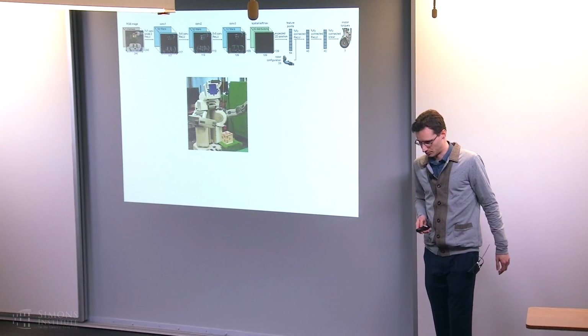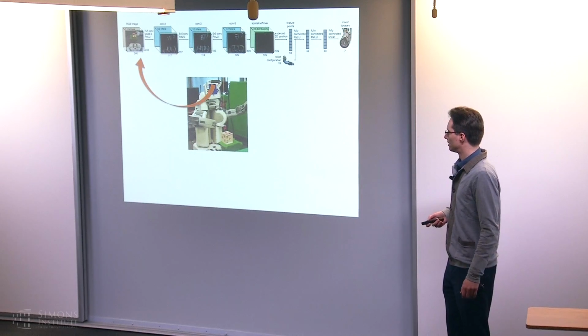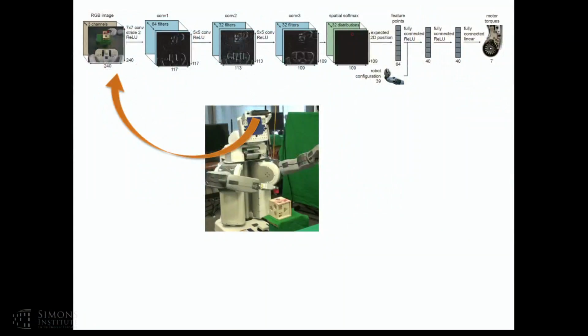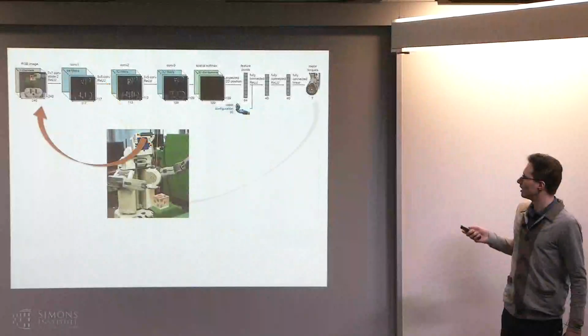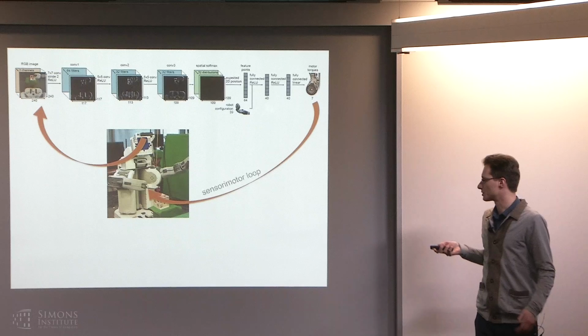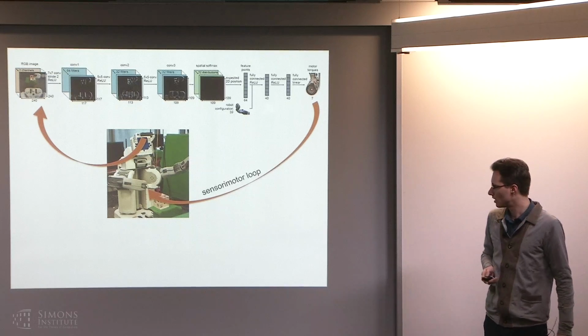So at a very broad level, we might imagine that the way we might control a cyber-physical system like a robot is that we might have inputs from the sensors, like the camera, feeding into some learned model, which may or may not be a deep neural network. I'm drawing it here as a deep neural network because those are the experiments that I'm going to show you. But so long as it's learned and it's end-to-end, that's going to be good. And then it directly outputs the actuation commands, which then go to the robot's motors.